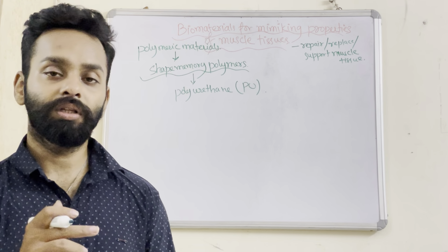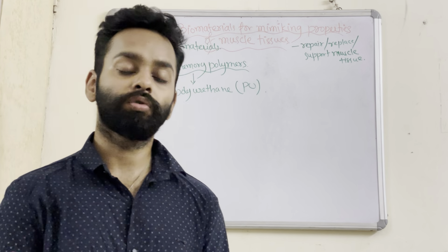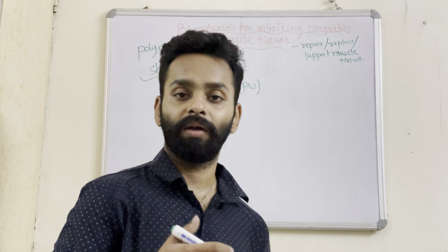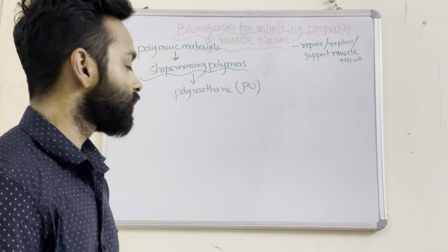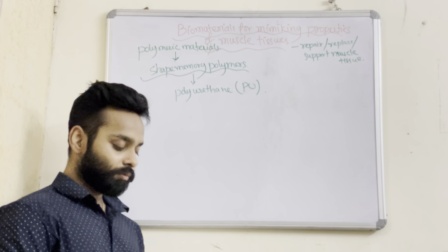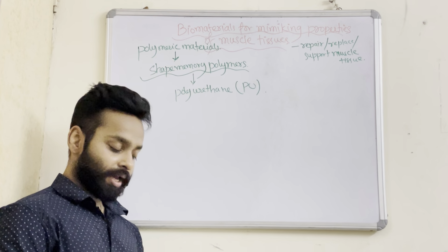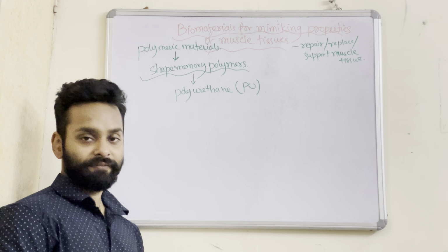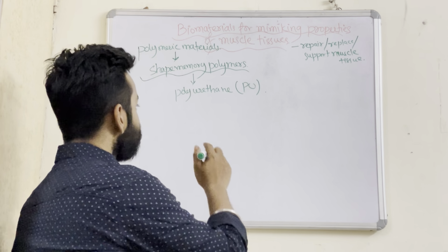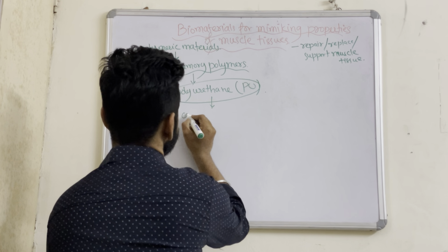So we need to tune the properties of these polymers or this polymeric composite material so that it can respond to this electrical stimulus, or show a shape memory effect or behavior through electrical stimulation. In order to make stimulation possible by an electrical or electronic field, which is closest to the muscle tissue, a composite can be prepared by adding conductive fillers to the matrix, such as carbon nanotubes. So we need to perform complexation.